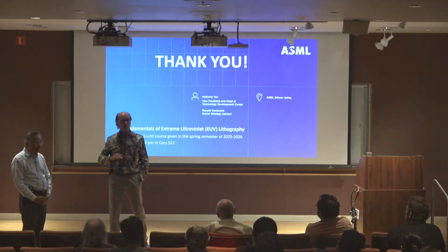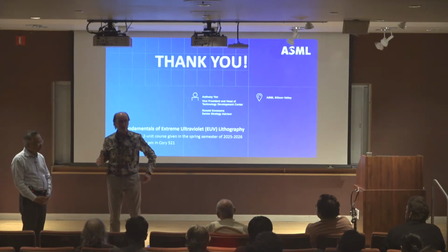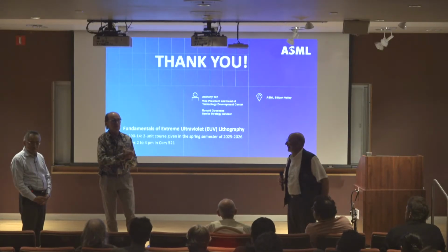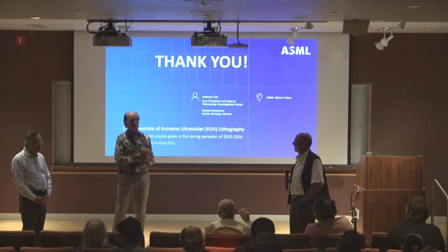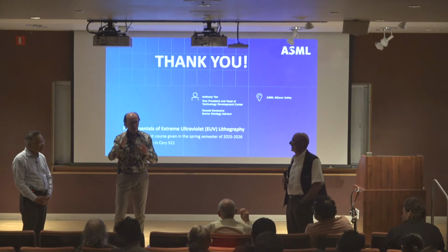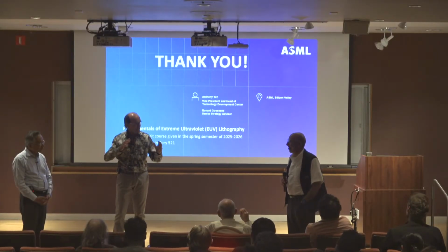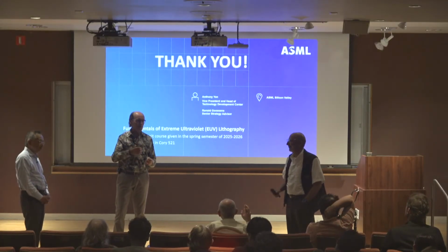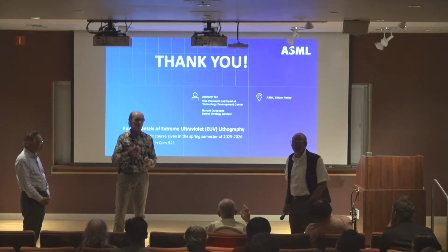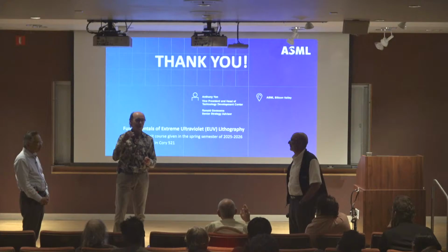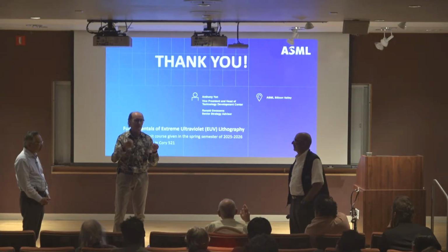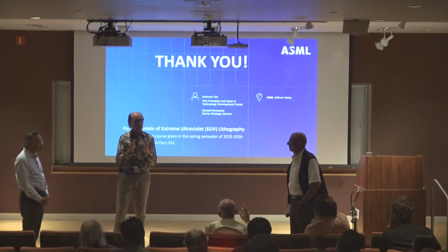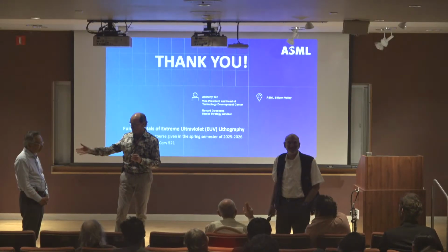Back in the days that we had the 45 nanometer node, that actually really represented the size of the lines. And at some point that became increasingly difficult, but people also became very creative with design tricks and layout tricks: I can get more density out of the size that I have. So think of the 5 nanometer and the 4 nanometer and the 3 nanometer now more as an indication of what is the effective transistor density, how many transistors can I get per square millimeter or per square micron. It's more an indication of that instead of really the dimension. Tony, anything you would like to add?